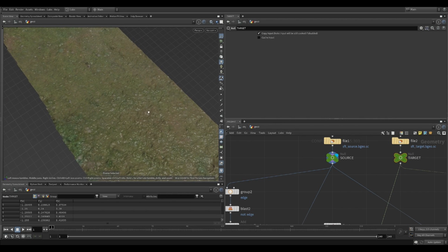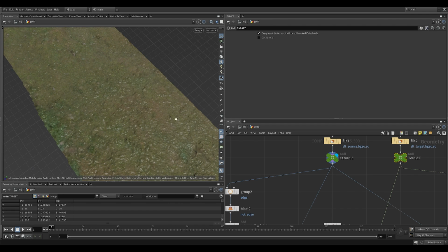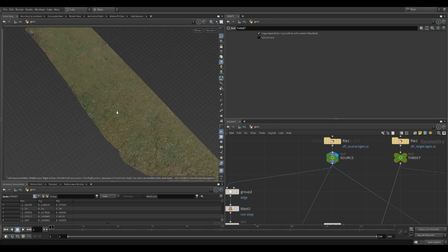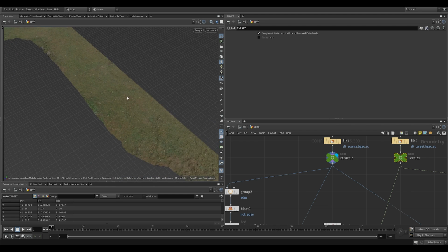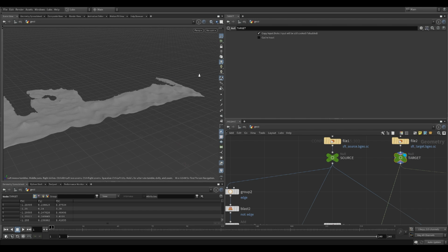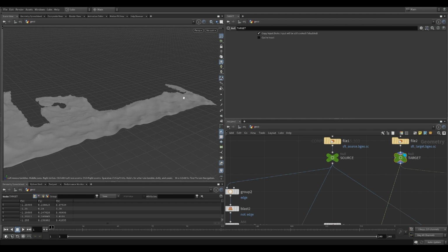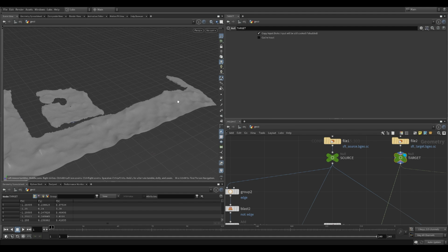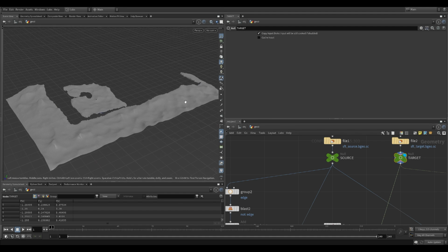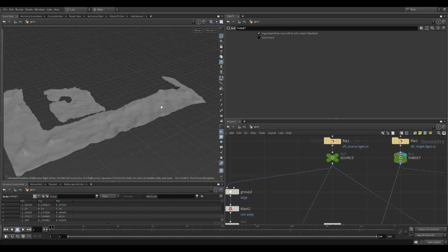So the idea is to create locations to sample this from, and for each stamp we're going to use a circle, and instead of using point number matching, we will physically move that circle over to a certain area above the target, then project that circle down so that it creates a proximity matching relationship. Then we're just going to transfer the detail based on proximity.